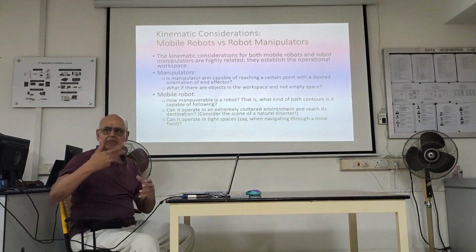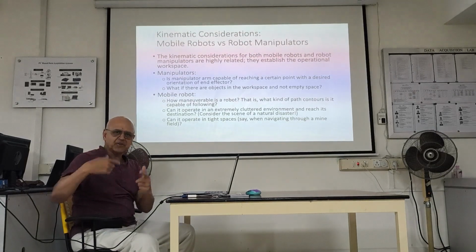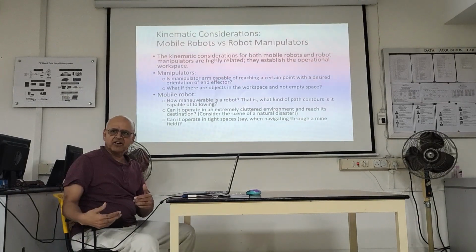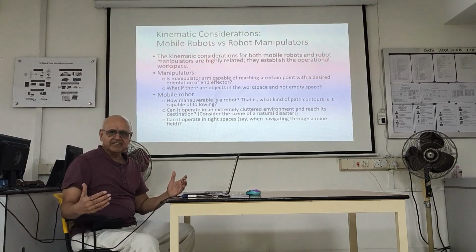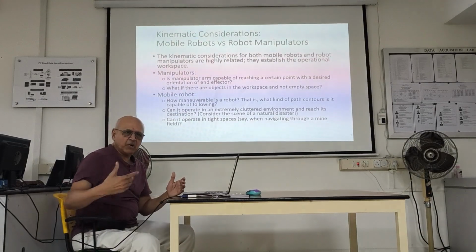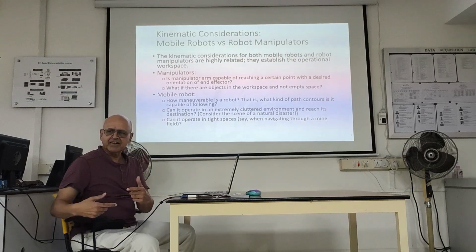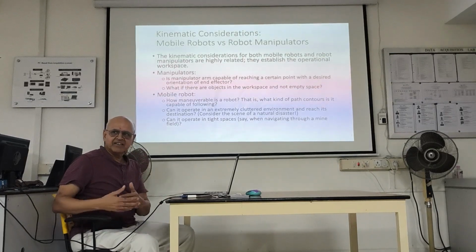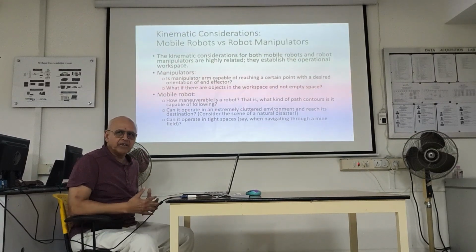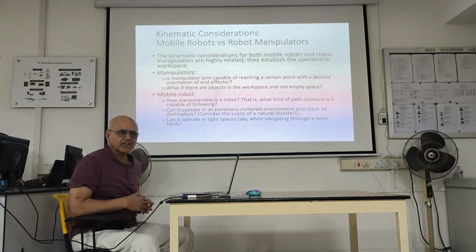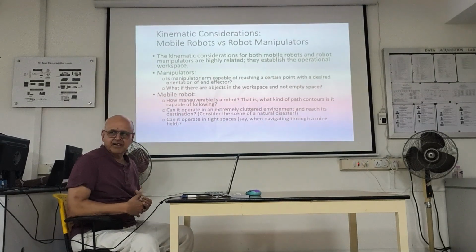Because sometimes when you hit a bump, the tire will come off the road, it will spin, odometry will be recorded, but it's really not making ground. So it doesn't mean anything when the wheel spins in the air. So you have to deal with all those problems. That's why odometry cannot be relied on for long. You need some kind of correction.